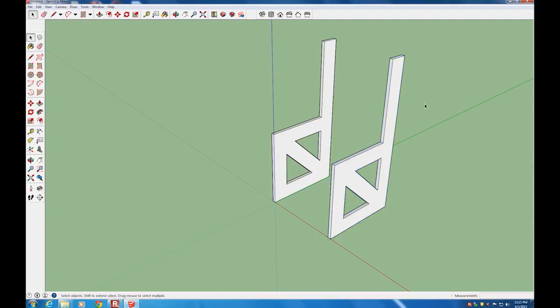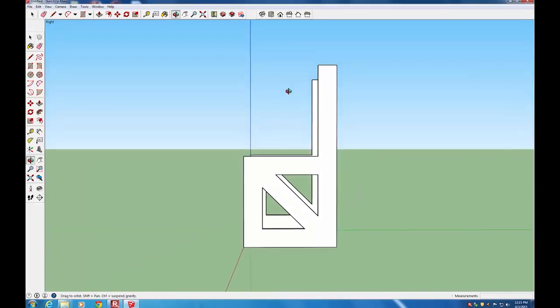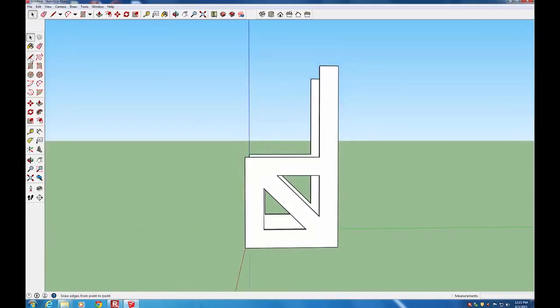So next, we're going to add some guidelines to the side of the chair to add the cross braces. So I'm going to switch to the right view so we can see the side nicely, and then start drawing these guidelines. So there's a lot of little lines here. The dimensions are in the handout, but I'm going to go over here 0.025 meters, and then down 0.1 meters.